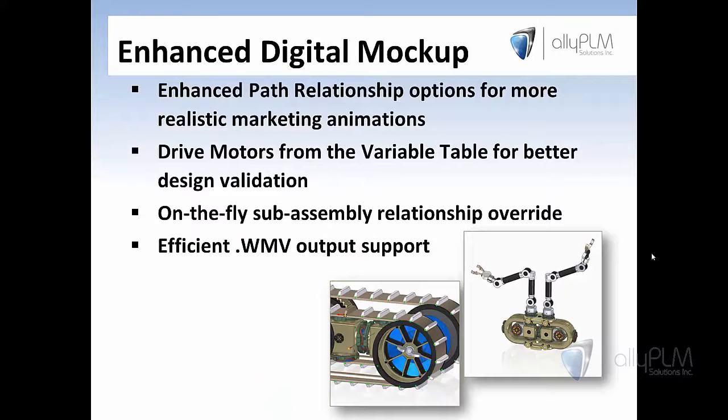Once again, we just checked out the enriched digital mockup inside of Solid Edge ST8. I demonstrated enhanced path relationship options for more realistic marketing animations, as well as how to use drive motors from variable tables for better design validation. We also took a quick look at on-the-fly subassembly relationship override tools and our efficient WMV output support.